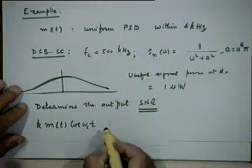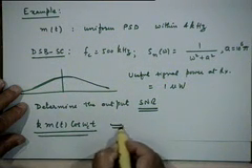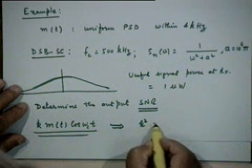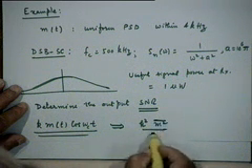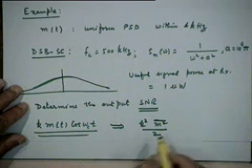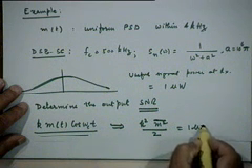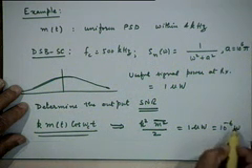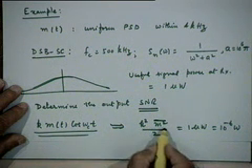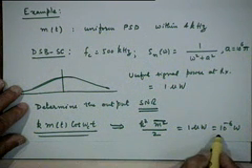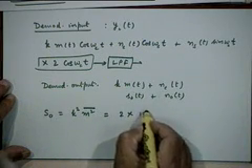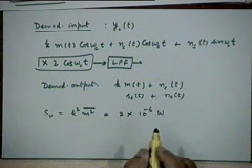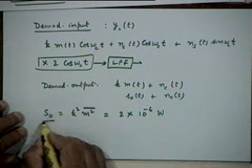What is the power of this? k squared m squared bar upon 2. So this is given to be 1 microwatt, which is 10 to the power minus 6 watts, which means k squared m squared bar is 2 into 10 to the power minus 6 watts. So S_0 is 2 into 10 to the power minus 6 watts. So output signal power is known.